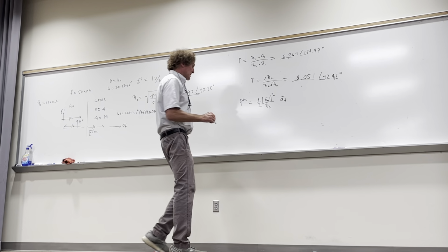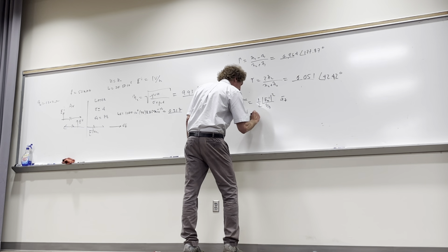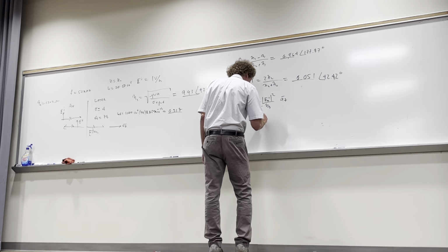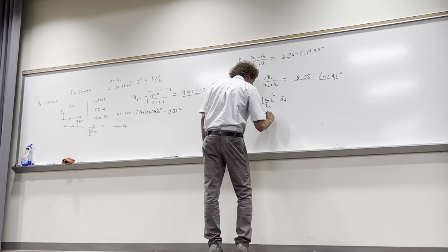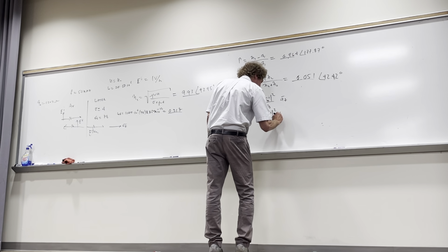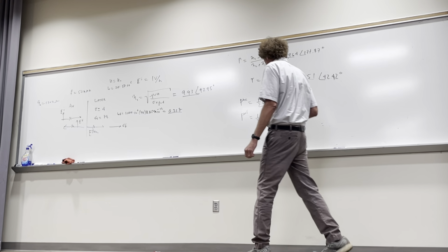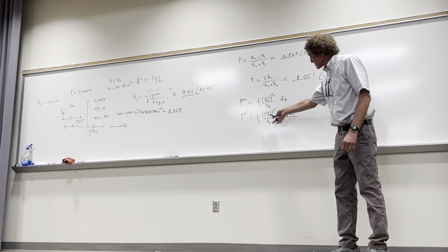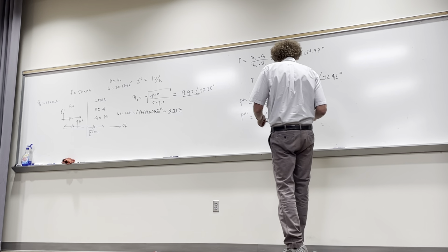The reflected power density, P reflected, technically is going to be 1/2 times the magnitude of the reflection coefficient times E naught incident, squared over eta naught. And it would be in the minus a_z direction if we wanted to be exact. But here you can see this is just the reflection coefficient's magnitude squared times the incident. So I can do it this way.